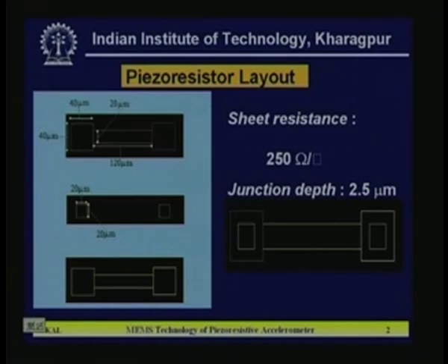So for designing an accelerometer, the end of the design process is making the mask. The mask was not discussed in my last lecture. Today I will first initiate the discussion on the fabrication of the mask, and then we will switch over to the technology development. Now for the layout of the mask,